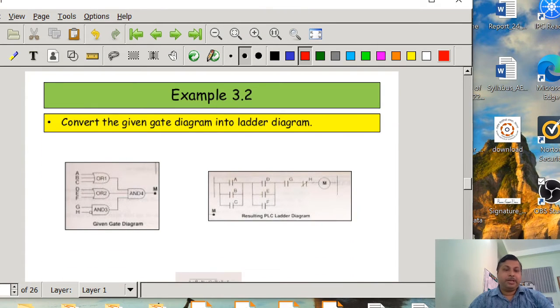Okay, so now here you see, to get the final aim, we are using an AND logic. It means that there will be no branch or no rung to realize the aim, because all this logic has to be true simultaneously to get the aim logic high. So that's why all these three logics have to be ANDed.